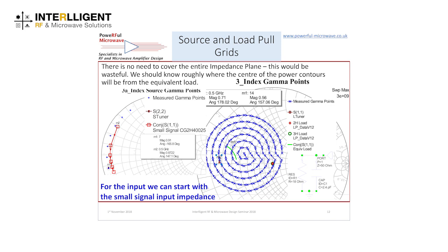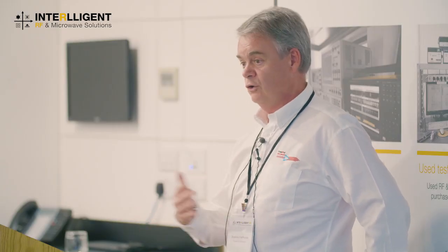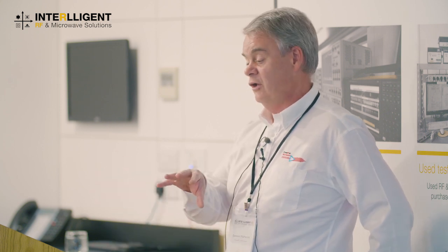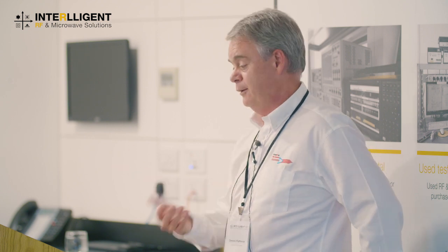Well, we use the basic Cripps method of what's the output impedance of the device, which we get from the power and the voltage we're operating at. The capacitance is on the data sheet. And if we plot that with frequency, we get this green trace here. We want to actually not center the load pull contours on that, because if you're going to work in a higher efficiency mode, you're going to work at a higher resistance. So we offset the contours a little bit. But don't worry, if you set up your contours and you find that your circles fall outside of this grid, you do a simulation and you recenter it.